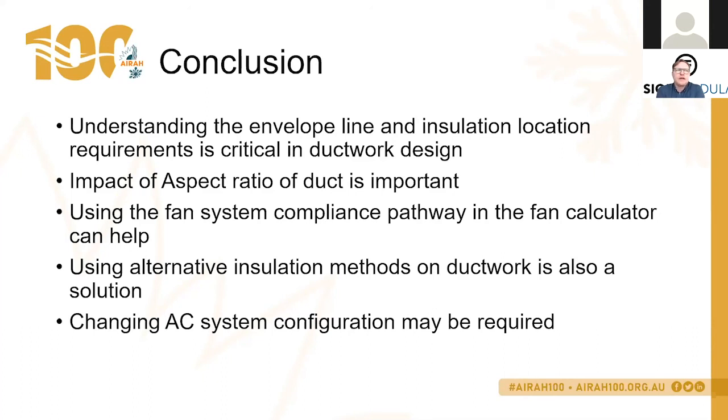What we did as a considered solution, using a bit of expert judgment, was decide that if we insulated and fully enclosed the top of the riser, and sealed it up where the ductwork went into the riser, so that the riser was separate from the plant room, then we would make the ductwork riser part of the conditioned space, because that actually made the ductwork riser smaller and allowed us to reduce the insulation requirement on the ductwork.